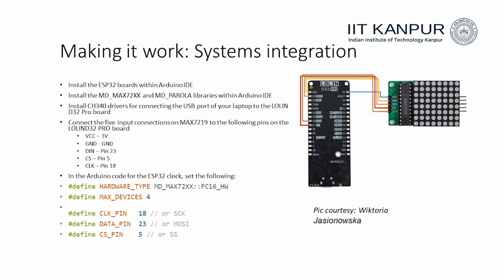So you can close your Arduino IDE, and it will still keep running, because this is directly connecting to my smartphone through this board, and it doesn't need to go through my laptop. All it needs is a source of power. So I can literally take this and plug it into a USB port, and if my Wi-Fi is running, it will show me the time.